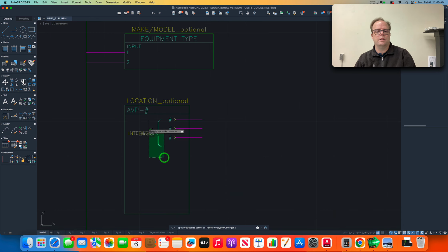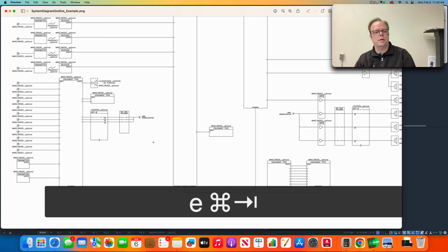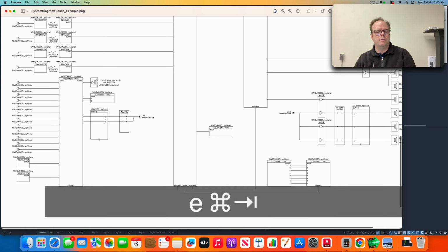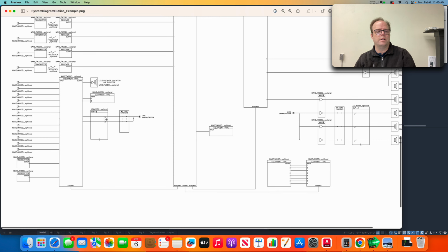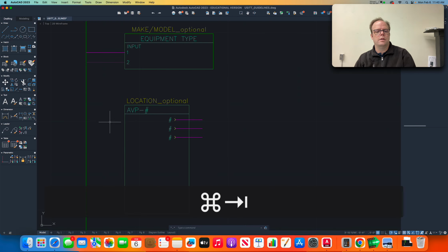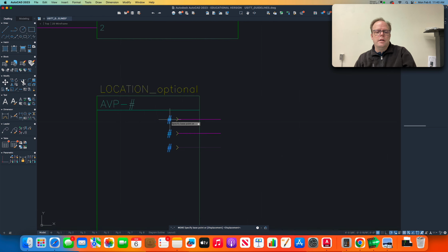And I don't need the intercom label or any of that. Yeah, the little number signs move down to the bottom, don't they? How could we do that? Well, let's select them and hit M, enter. And let's just move them. This is kind of an eyeball thing as well. Move them a little bit underneath there and click.